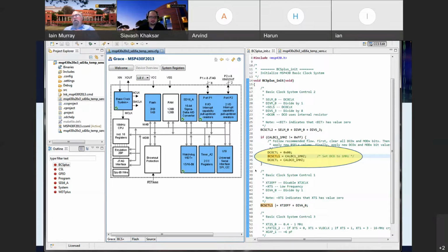So having the code running slower and still being able to perform within the deadlines that you have is a major power saving. And you need to be able to have very tight control over the hardware to be able to do that. High level languages don't always produce the best code. So the ability to insert the assembly language where you have a particular hotspot, where you spend most of your time processing, and optimizing those areas of code can make a significant difference to the power footprint of your device. The other one is also, of course, to shrink your code size down.